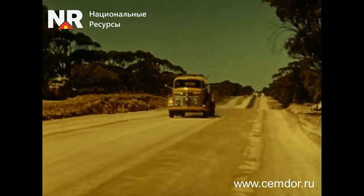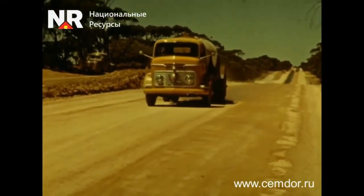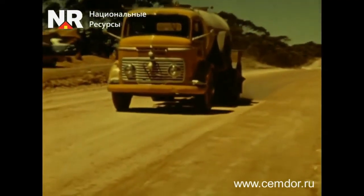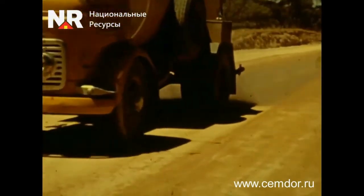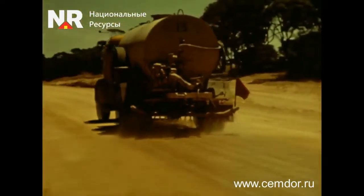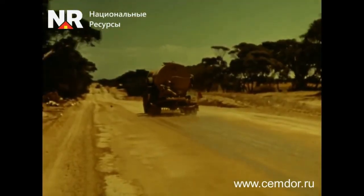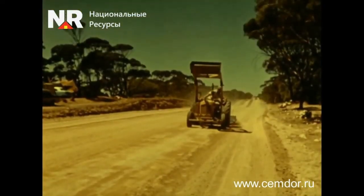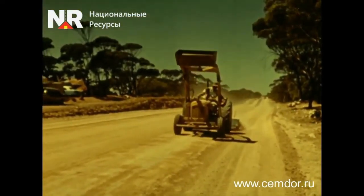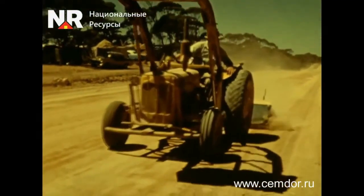The moisture content of the soil during the construction of the soil cement layer must be kept at the optimal proportion. It is also necessary to maintain the moisture of the laid layer until it is covered by the next layer. Watering after the stabilization process is essential to prevent the road surface from drying out. After this, the surface of the soil cement road pavement is finally profiled to eliminate minor irregularities.